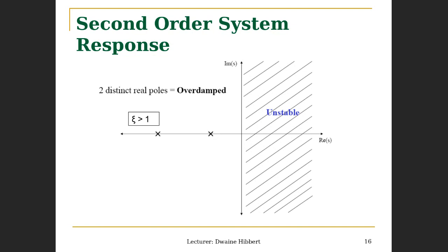So if you take a model for a system as a transfer function and you extract from it the denominator, which again I say is the characteristic equation, that equation will fully describe the behavior of the system. That must be noted.